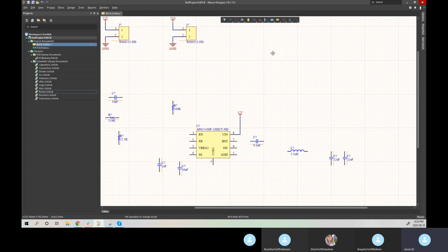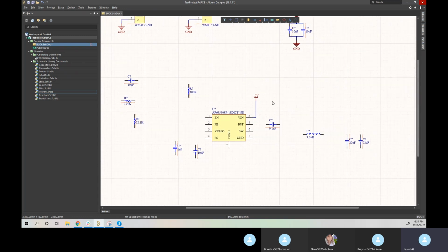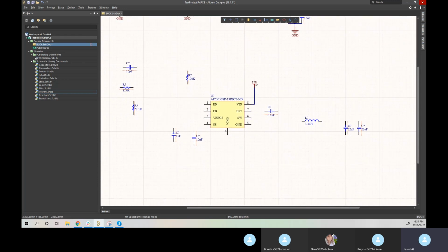When you have designs that have a lot of bypass caps, it can be especially helpful. But even at this stage, we can give them the power ground connection they need and then throw them off to the side so they're not going to clutter up our design. So we'll go with that. So all we have is our 12 volts coming in.